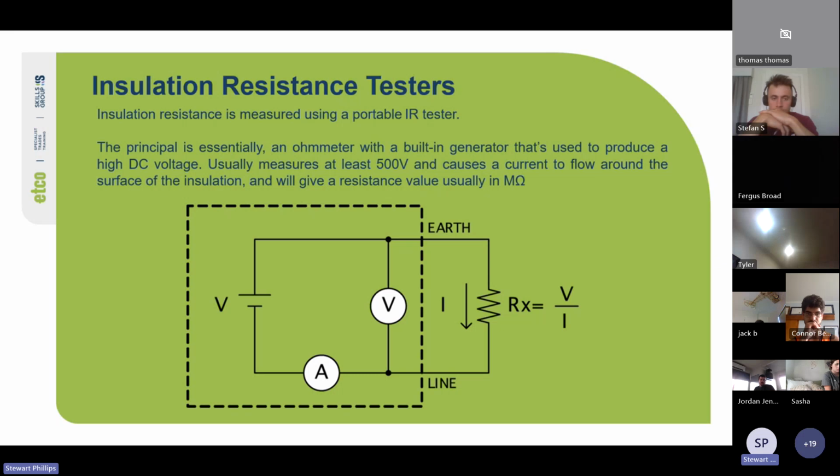One great way to find a fault, if you're getting a fault on a circuit, is to switch it to 1000 volts DC, hook it up and leave it running. Either the fault will clear itself or it will pop and you'll be able to find the fault. It's not always a good idea, but it works in a pinch.